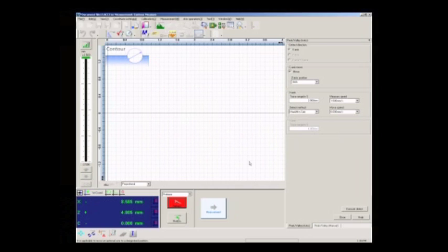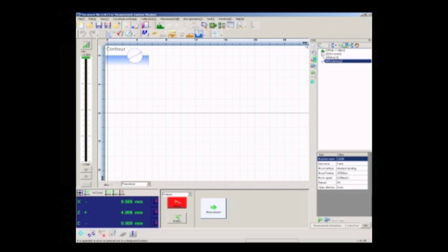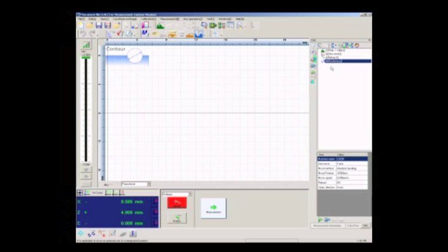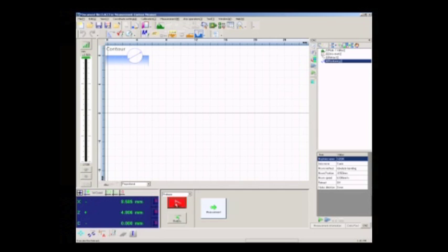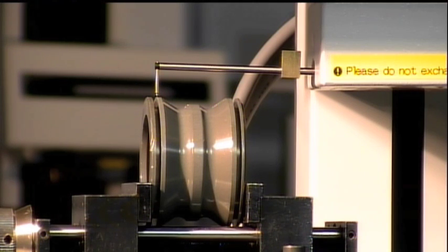And we'll actually execute the move, even though it doesn't move very far, so that it records in our program list up here. Okay, so when I'm looking on the right-hand side here, I see all the steps so far. I see the peak valley detection, zero reset, which you did manually, right? The retract, and then positioning, getting ready to start the scan. That's right. So before we start the scan, though, we want to make sure we drop that stylus back down because it's still raised up. So we'll release it, and that releases it down into contact with the part.